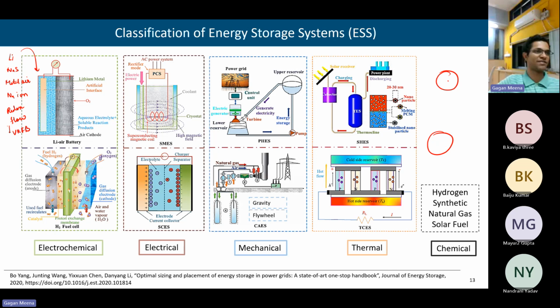Already it is full and monsoon is there, we can simply generate, keep on generating and fill it here. But now because you cannot pump it, you cannot generate also because the lower reservoir is already filled. So in monsoon, its capacity is reduced, because if both are man-made, then that problem is not there.